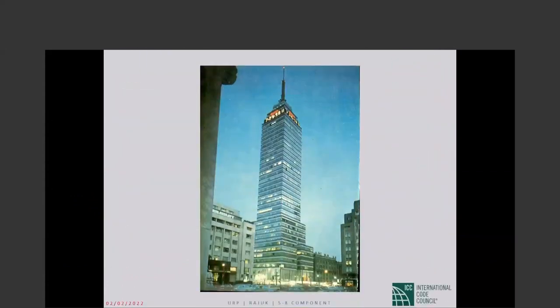That's about all the damage that you could see. And at the other range of the spectrum, this Latin American tower, 40 stories tall, so 4 second or so period. This was out of the range of the earthquake. Predominant period, remember, was 2 seconds. So short buildings were not affected, tall buildings were not affected, but the mid-rise buildings paid a huge price.